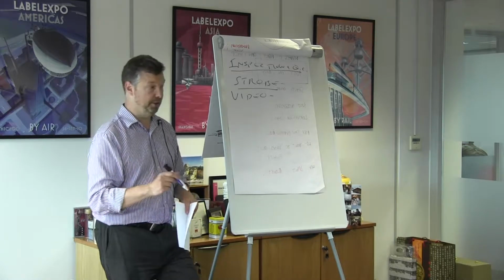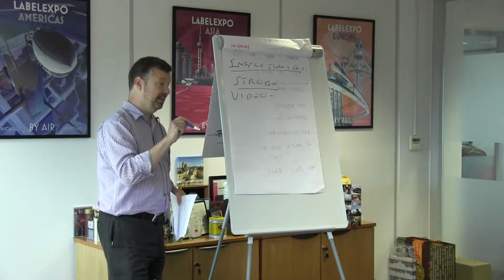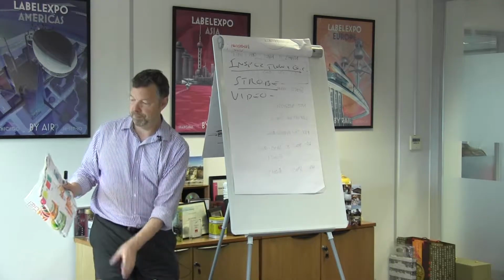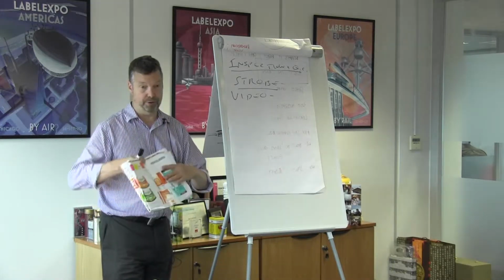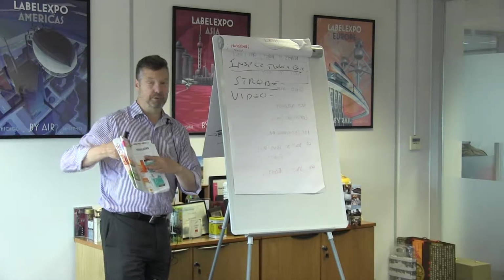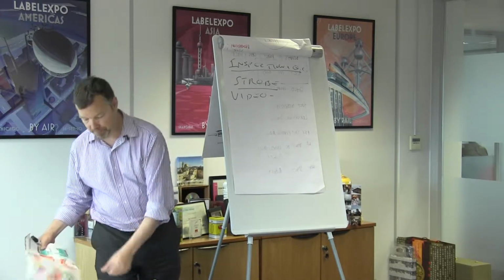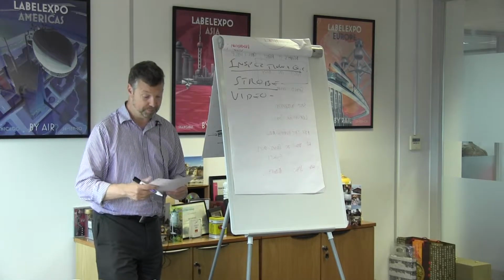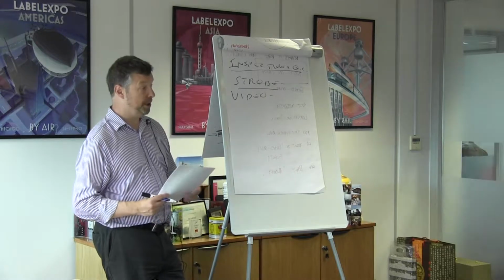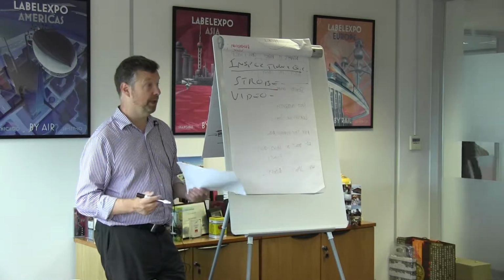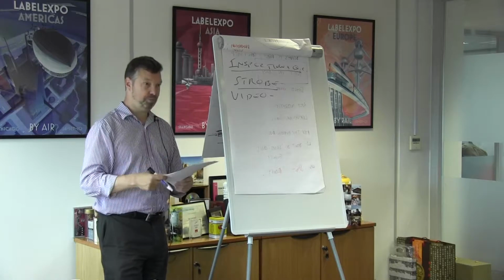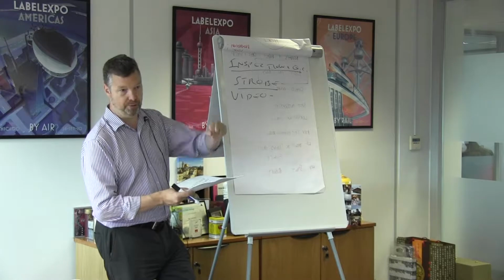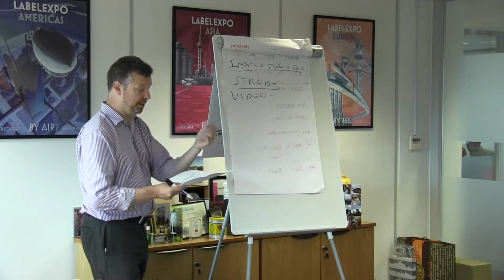The other thing that it's not very good at doing is checking color. It's not really saying that's the orange that I'm checking for. What it's really doing is just checking for obvious printing mistakes. The kind of printing mistakes are print defects, pinholing. Pinholing is where for some reason there's something on the plate stopping the ink getting onto the material, leaving little holes in the print.